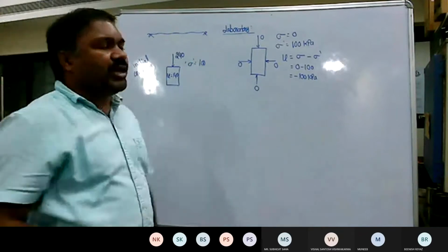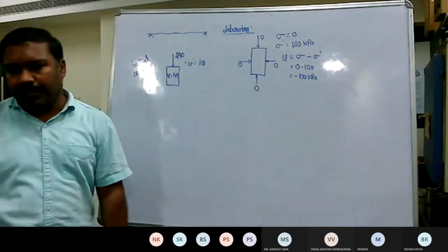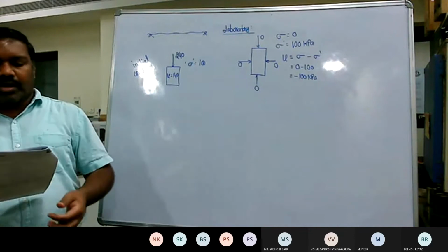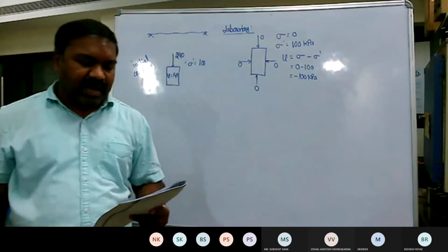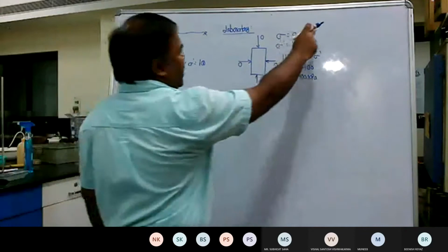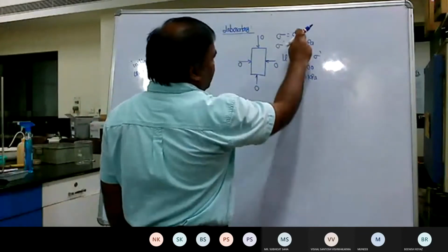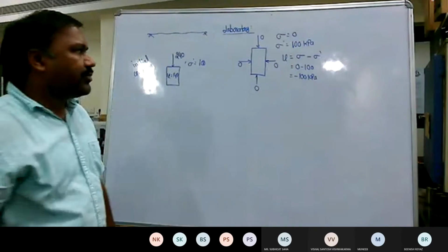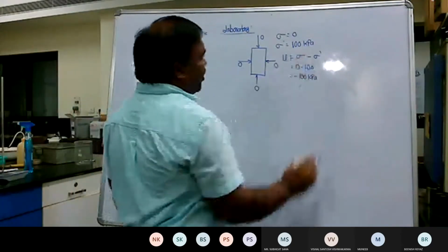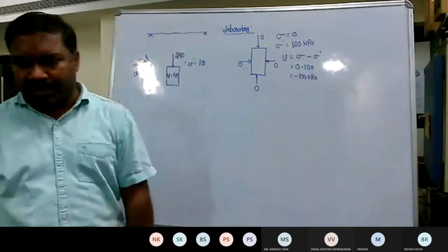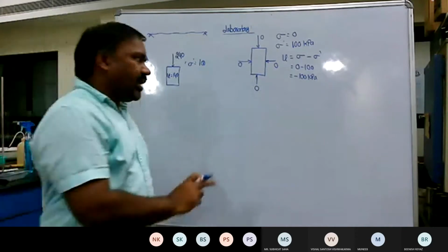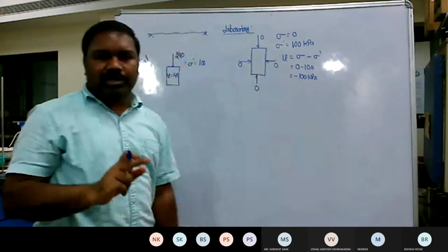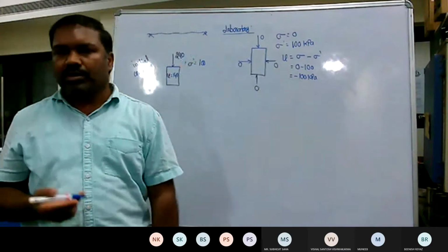Okay, you need to understand very carefully. What are the changes that are happening? On sampling, what are the stresses acting on it? The total stress is 0. Effective stress remains as it is, and the pore water pressure will change. Here the inherent assumption is that there was no change in the water content, no change in the void ratio, therefore there was no change in the volume.